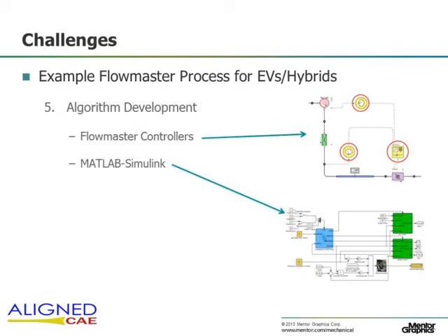Once we've run our transient simulation and we've optimized our components, we look at algorithm development. There are a couple of ways to take care of this with FlowMaster. The first one is using FlowMaster controllers. In this case, the algorithm itself is developed inside of FlowMaster.